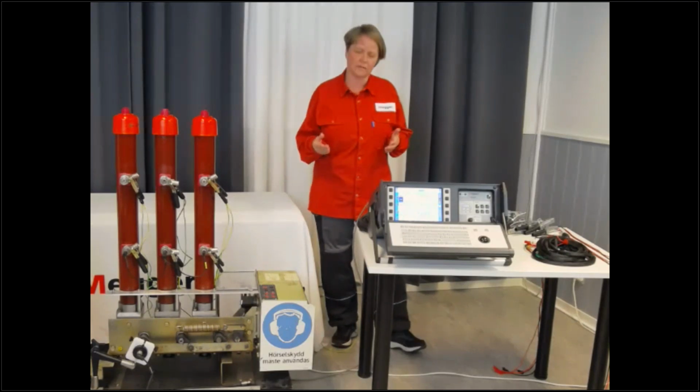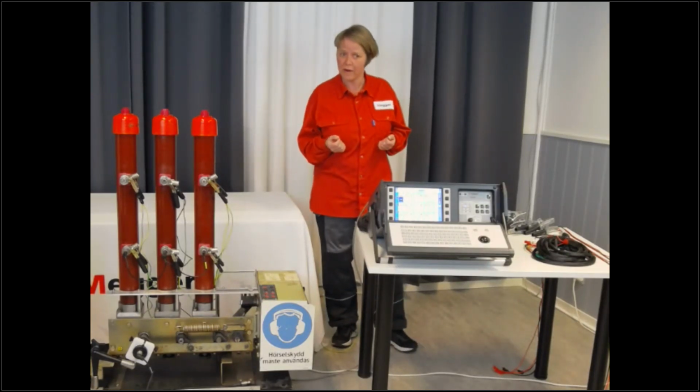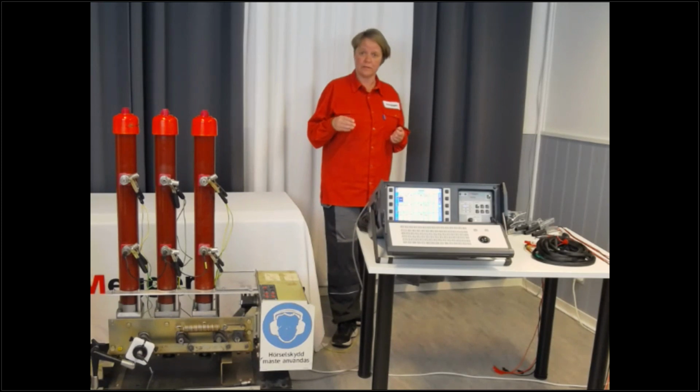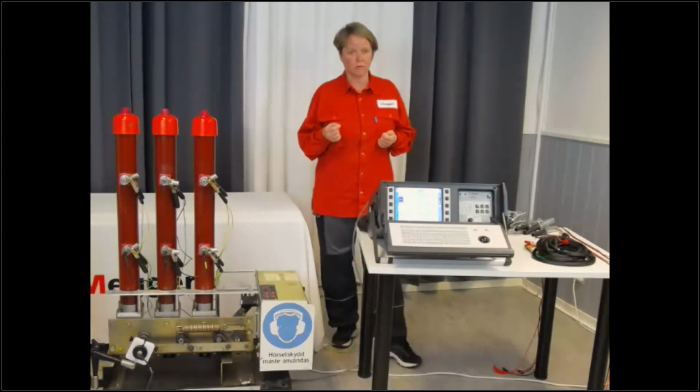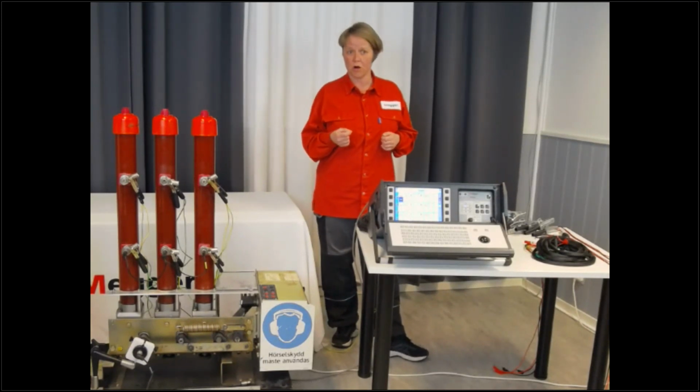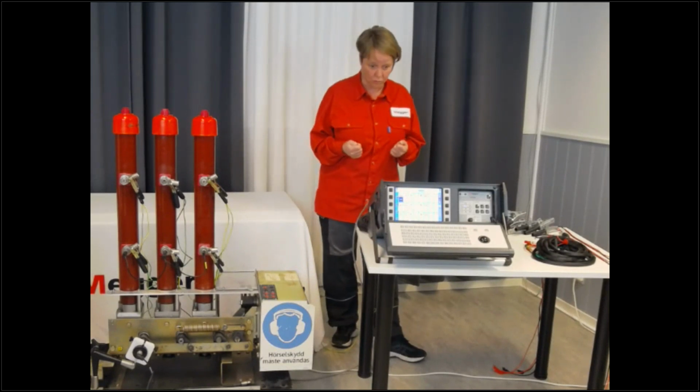What do we do then? Again, we're using these ferrites to separate the groundings. ABB, for example, commonly have a star ground point, and you can put the ferrites over that star and actually connect directly on each side of a ferrite. That sounds really strange, but it works.